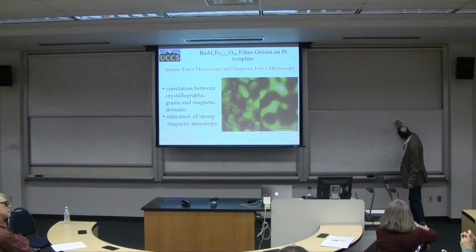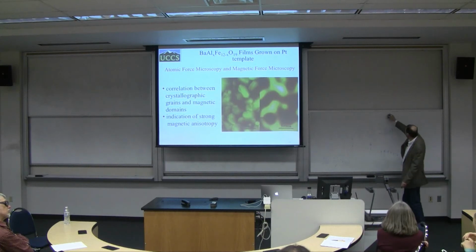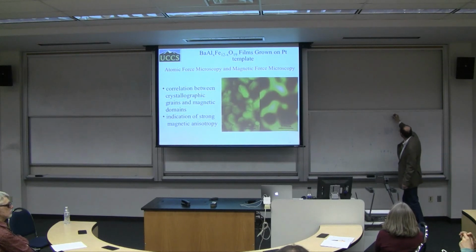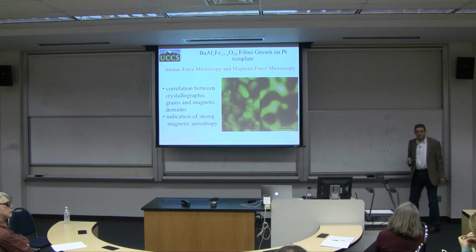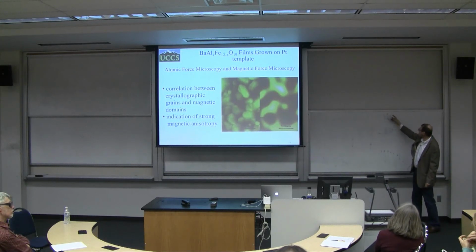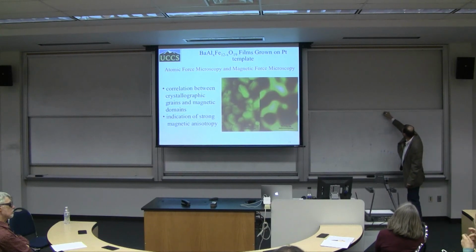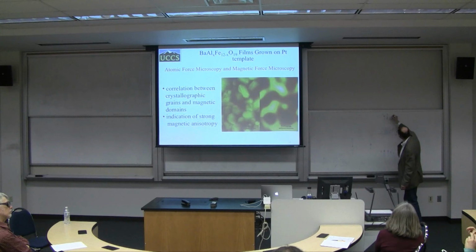So you have moments like this, and you have here a reading head, which consists of two different materials. One of them is always, let's say, up. The second is soft, and can switch between being up or being down. So these layers can flip. Now imagine that you are driving a current which goes here, and you are picking up here. Depending on the orientation of this layer, if it's up, you have one value of resistance. If it's down, you have a higher value.